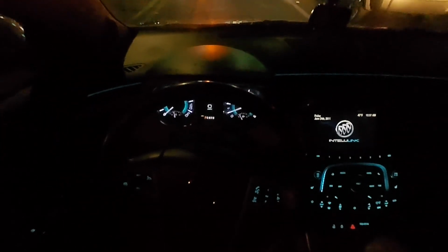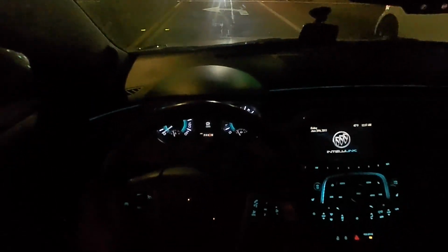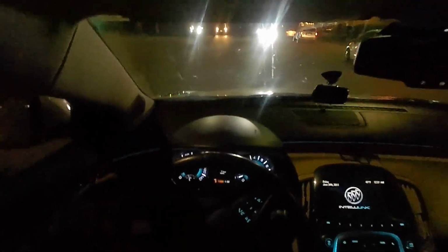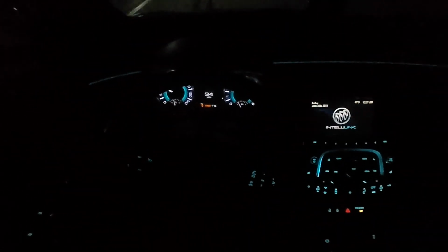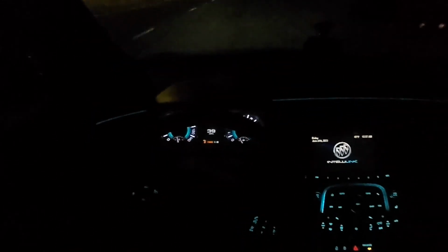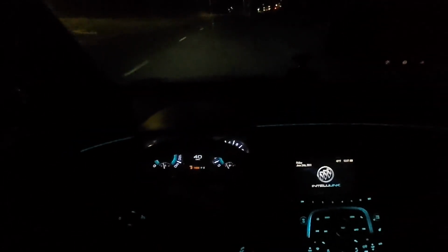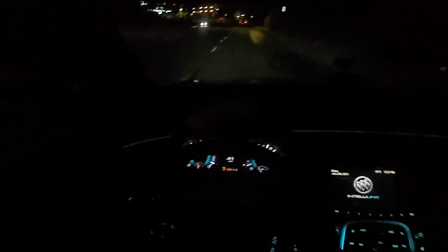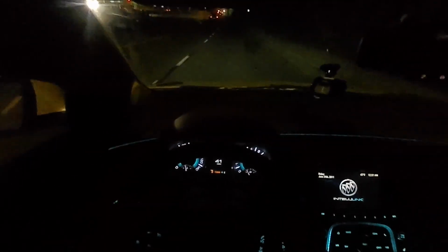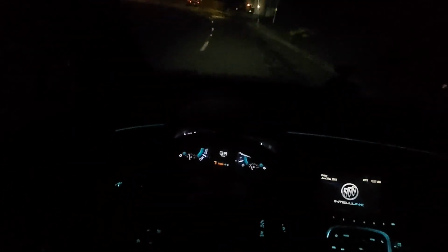Now the idle reading is pretty stable. It's steady on 1000. I haven't seen any vibration in the engine or the car as I used to before. Just accelerating a little bit right now to see if there are any issues with the power from the engine as far as air and fuel mixture.